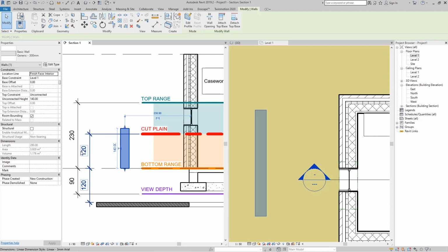If I have here a 112 and set this wall to maybe 199, you can see we again don't have the cut line here. But if I set here to the 200, now you can see the Revit show this thicker line, which represents that this wall has cut.